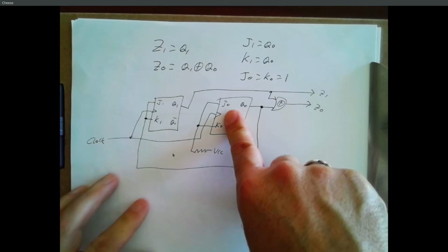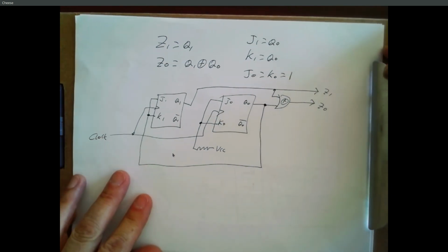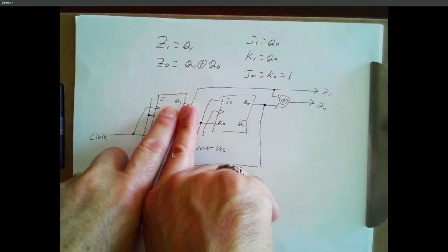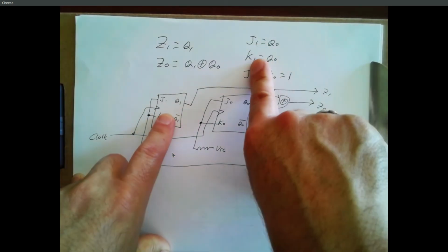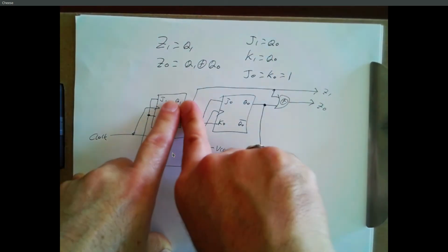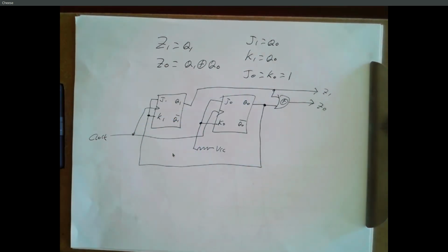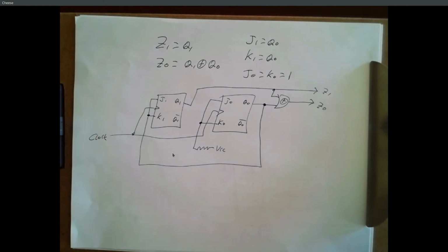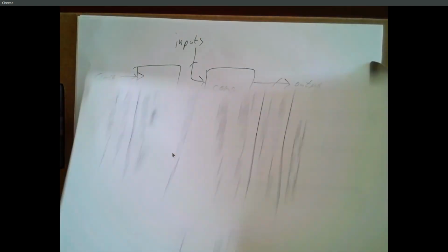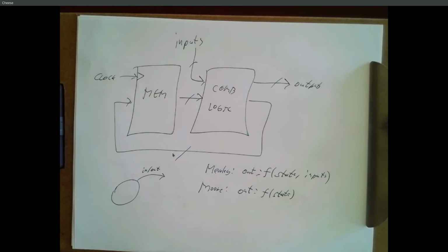And from that you can know what flip-flops do, and so if J1 and K1 are such and such values, you can figure out what the next values of the state are. And from that you can fill out your state transition table and then draw your diagram from that. So that's the analysis direction. The synthesis direction we did, which was take your diagram, state assignments, turn it into a transition table, and then draw your circuit.